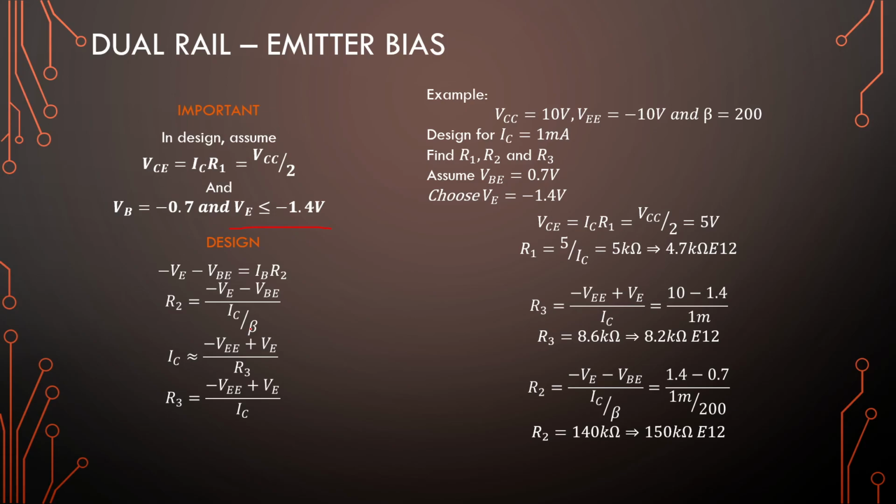You can choose a resistor 2 as your heart desires as long as enough current can pass through that resistor into the BJT. Okay, so there is an equation where you can calculate a good value for it, but you can pretty much choose anything and it will work. I will show you in the simulation. It will yield kind of the same values for the collector current. You will have offsets, but if you have an input capacitor on the input, the offsets are not going to matter that much.